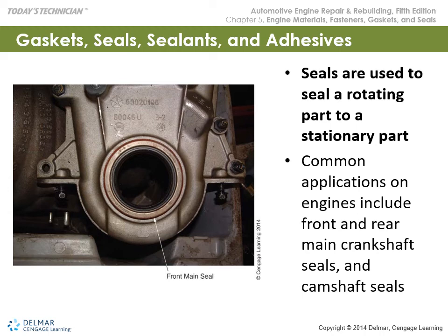So you do see some advancements in the application and the design of seals, so seals can last the life of the engine. So crankshafts and camshafts and water pumps and applications that have rotating parts are going to have seals, and you've got to make sure that everything's clean and there's a coating of lube oil on that surface when you do your assembly.